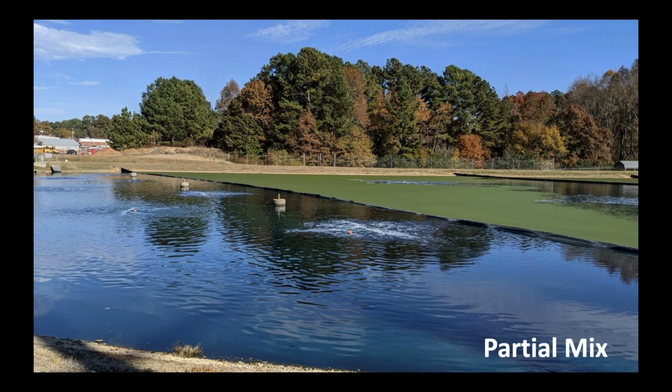It's about, I think, over 2 times the speed of treatment versus a facultative lagoon. So if a facultative lagoon needs 120 days of hydraulic retention time, an aerated lagoon needs about 25 to 30 days. So significantly less time because of the air mixing input that you get with these systems. The vast majority of aerated lagoons are what we call partial mix, and they look just like this. This is actually a facility in Georgia that we upgraded.